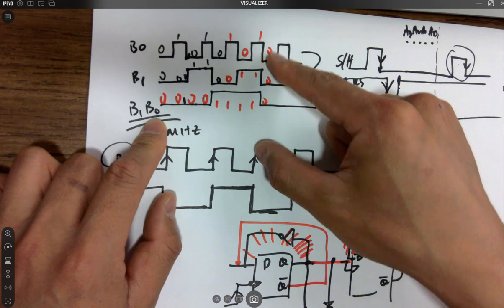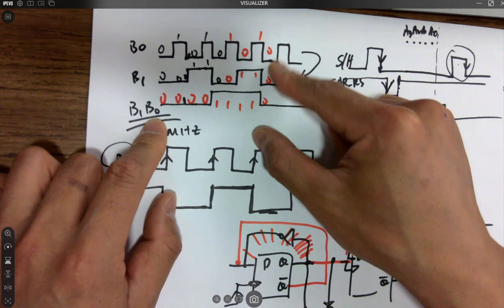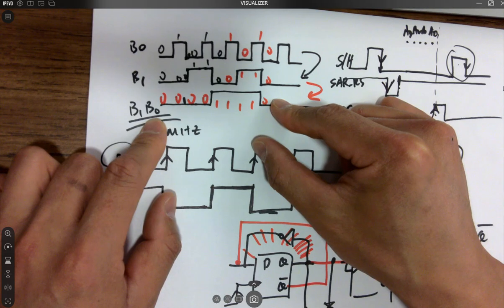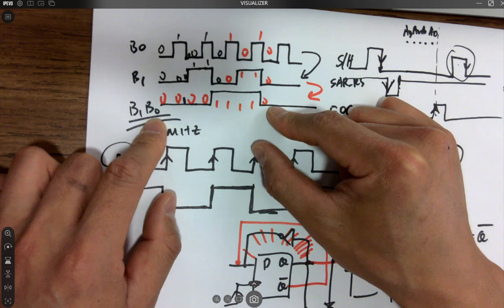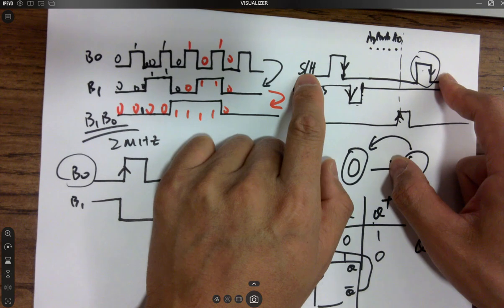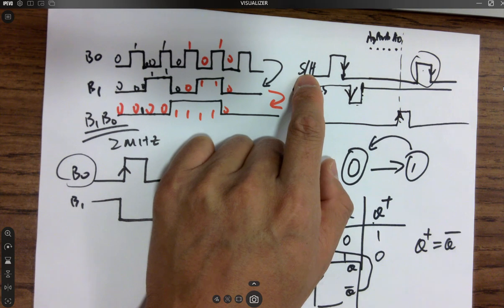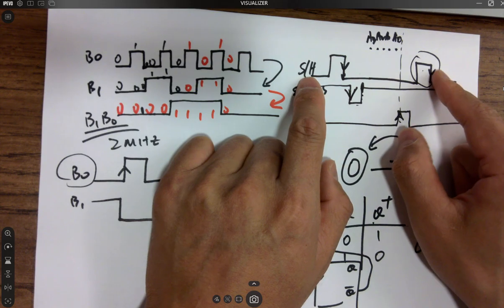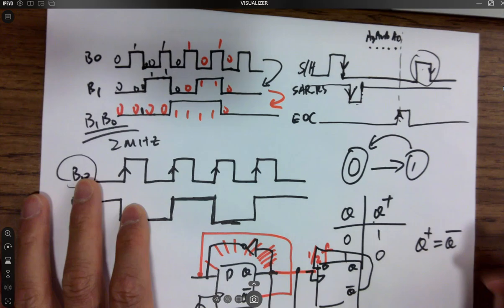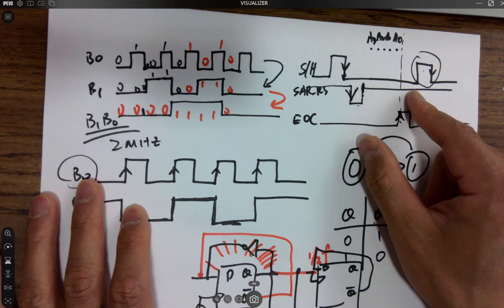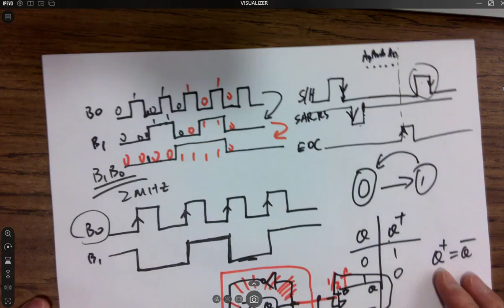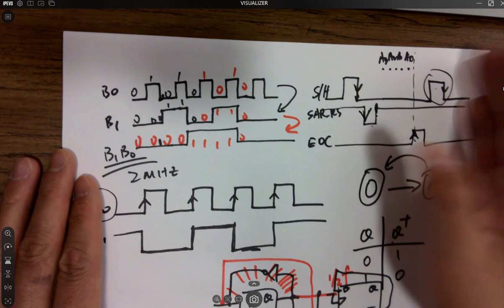However, you can control it to only let it count to a certain value, and then force it to reset to start counting from 0. That's required because we don't necessarily have to count until 16 or 15. We have 4 bits, so it's going to be 15, but we're not doing count until 15. We want to end it earlier. This I think is for 4-bit, it's probably like 7 or 8. Okay, so we want to count to 8, and then we want to reset.